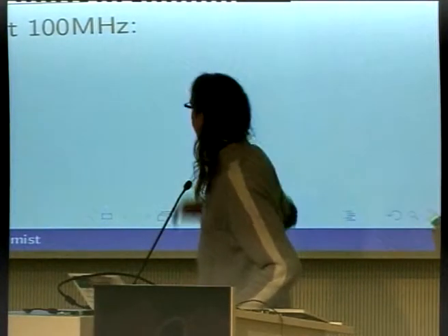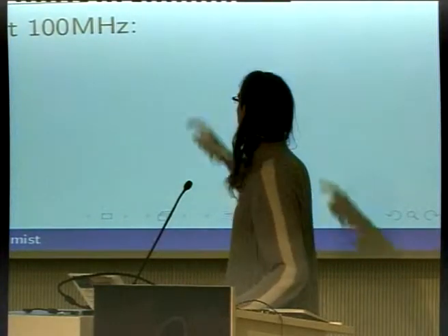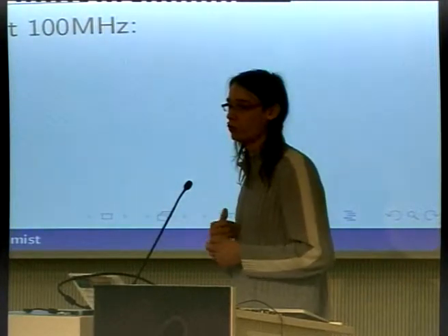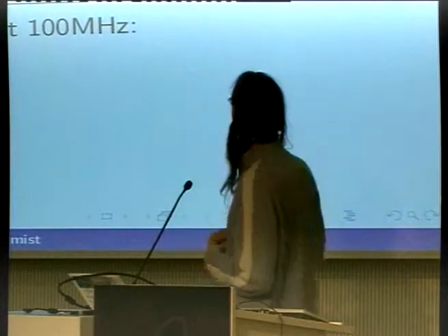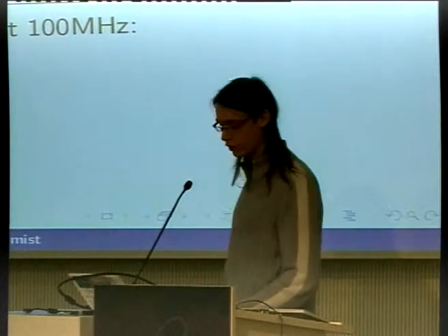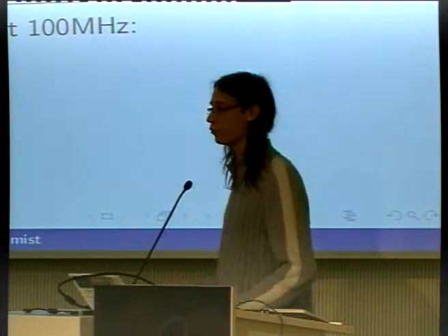So if you sum up all this, you see that the memory chip must have a sustained bandwidth of 2.2 gigabits per second. So between the FPGA or the custom chip, if you want to make one, you will have a continuous flow of data, which amounts to 2.2 gigabits per second, and the total capacity of the memory is approximately 22 megabytes. That's only the basic system that you will need. So let's see what the memory market has to offer.